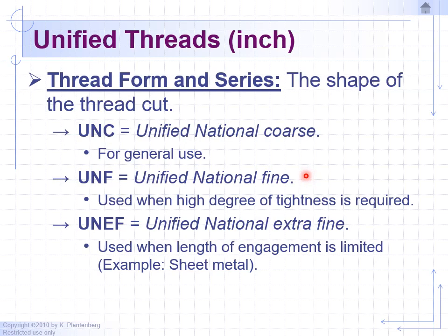So in some situations where you have a lot of stress, a lot of forces applied to your bolts or to the holes or the threaded nuts, then we want to use fine thread, especially when we have high RPMs. One good example are the wheel studs. So if you ever change a wheel, a tire on your car, you have to remove the rim. There you're dealing with UNF threads. Fine threads, they're tighter, closer together than coarse threads.